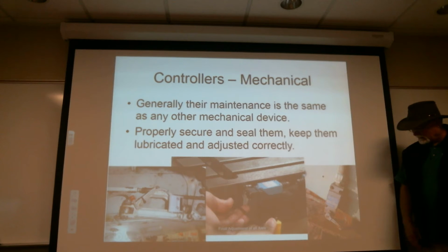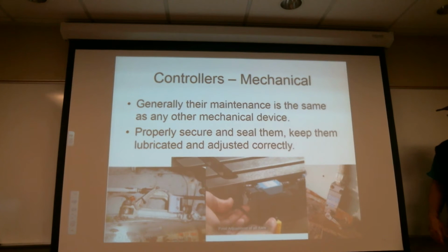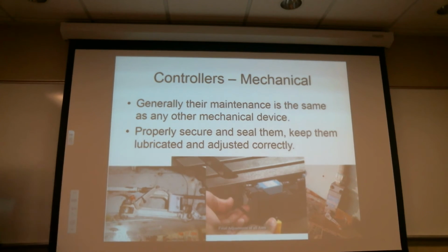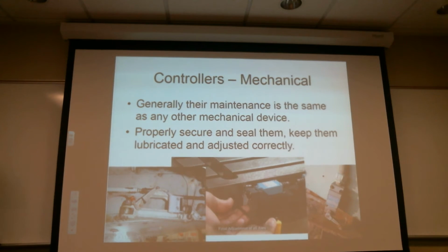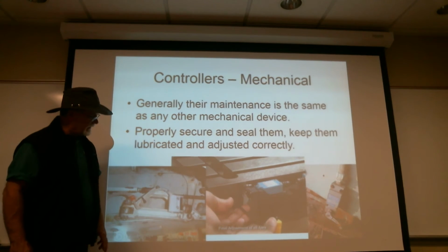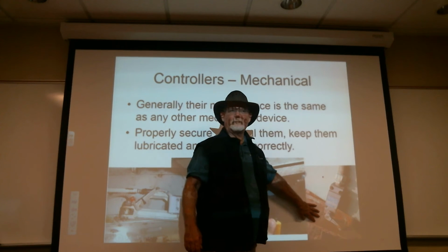This picture here is actually a hangar door. Again, this is a big AC, and all this one is doing is saying, okay, you let the door go up too much, it's going to break off if you go any more. We're going to break things, so I'm going to disconnect you. And what it does is, if it's not designed well, it'll disconnect the up. It won't let any more up happen. You can still do the down, but that's it, you're done on the up. Now note, that actually looks like a fairly new switch, well adjusted, nice and clean. This one's really nice and clean, well maintained. This one, not so much.